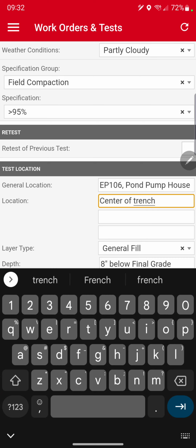If it was a wide trench and say I was 4 feet off to the left, I would say like 4 feet off center line of trench, that sort of thing. But I was straight in the middle because it's about a 1.5 foot wide trench. Center of trench, 2 plus 75. That's like 200 feet plus 75 or so. And that's in reference to the stakes.